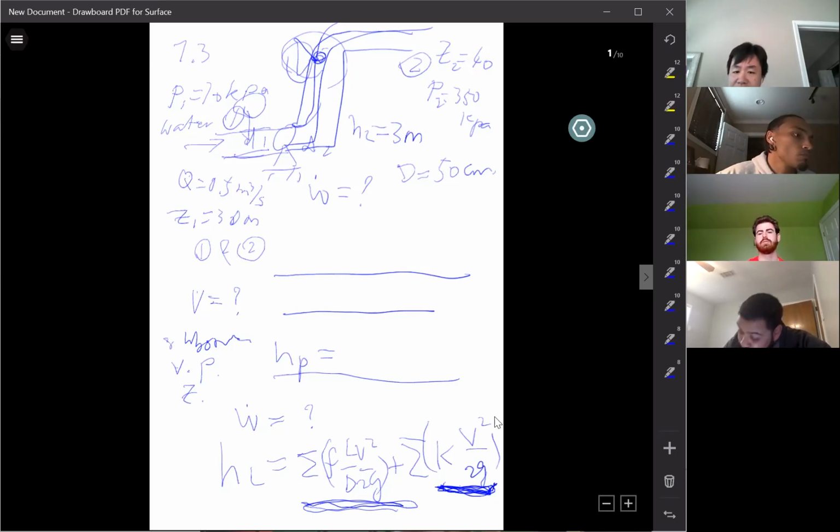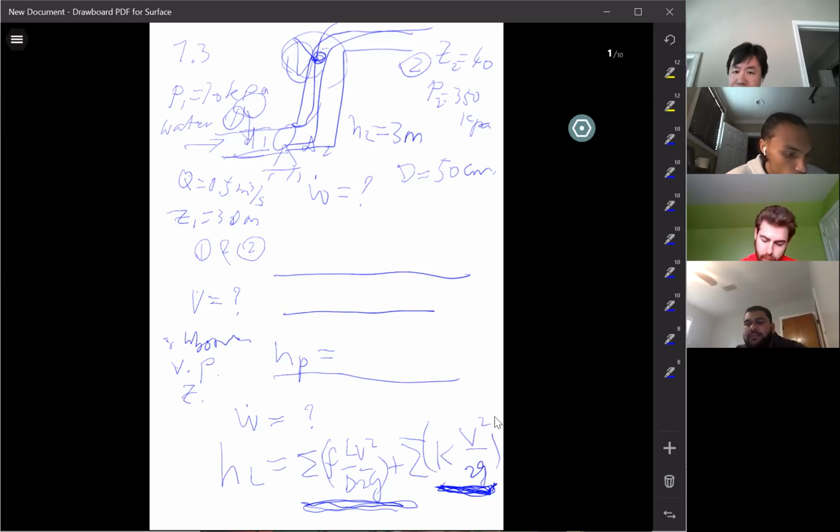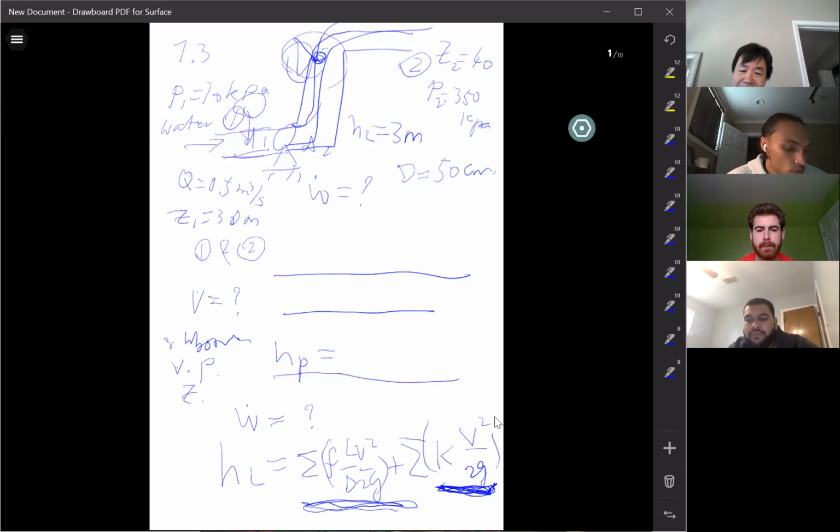Do you sum up all of the friction losses? Yes, if you have different portions of the pipe with different diameters, you have to calculate each section separately and sum them up. I'm mainly talking about reading those charts, the last step. The first step is to find the surface roughness, then go down and find the F value. Would that be a summed F value? No, each portion has its own F. That's why the summation is outside the parentheses in this equation. Oh, okay. I just wanted to make sure. Yeah, very important, very good question.